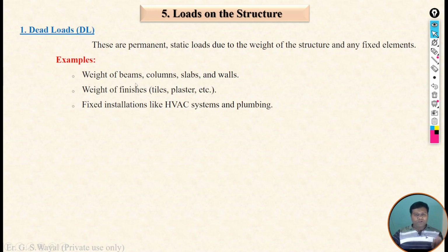The weight of beam, column, slab and walls comes under the dead load. Weight of finishes, meaning we are providing tiles, plasters, or any concreting or waterproofing material on the floor, also comes under the dead load. Then fixed installations like HVAC systems and plumbing: whatever HVAC and plumbing systems we are using, those loads also come under the